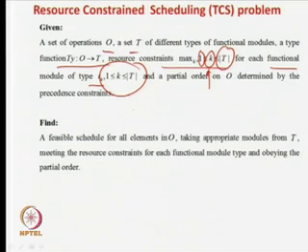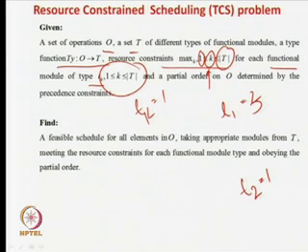It says that Tk, say, you can say equal to 1. So, that means for a particular type of hardware operator, if we say T1 may be the adder in this case, we can say that T1 is equal to max of T1, say 2. So, it says that a maximum of 2 adders can be in your circuit. If I say that T1 equal to 3, then a maximum of 3 adders is possible. Similarly, T2 stands for a multiplier. So, you can say that T2 equal to 1. It says that you can have only 1 multiplier in this one.